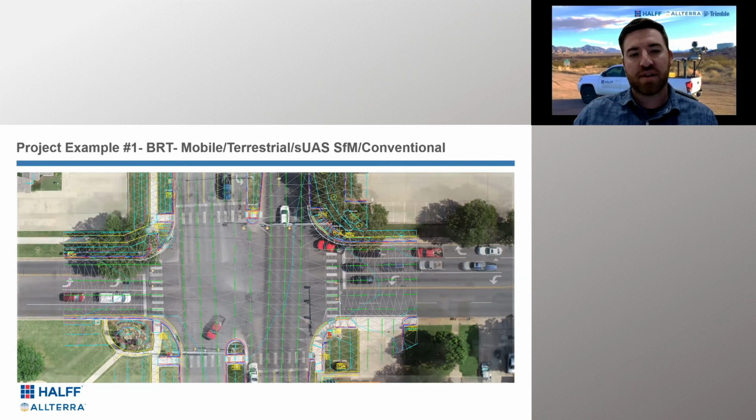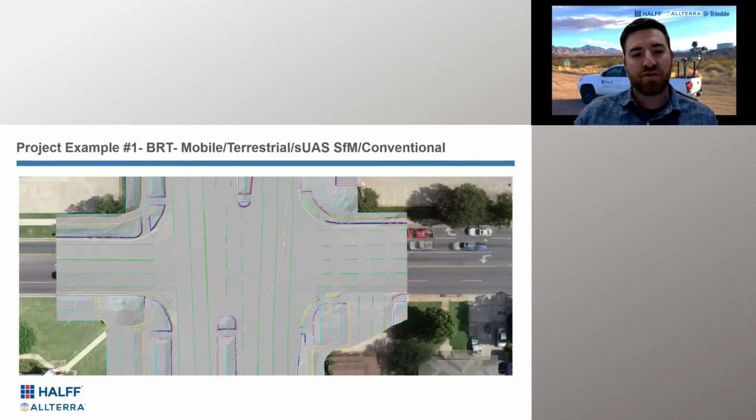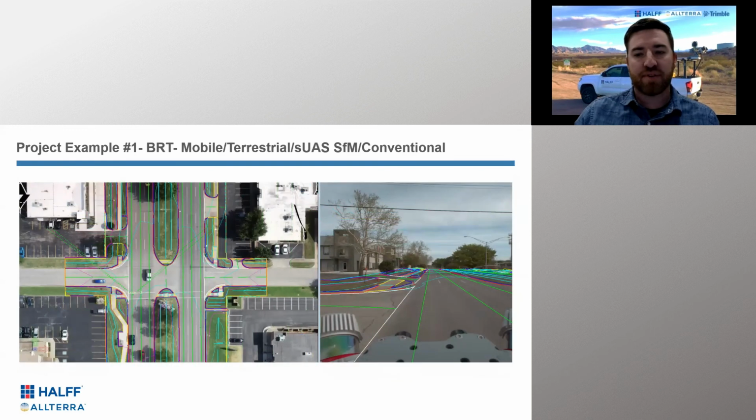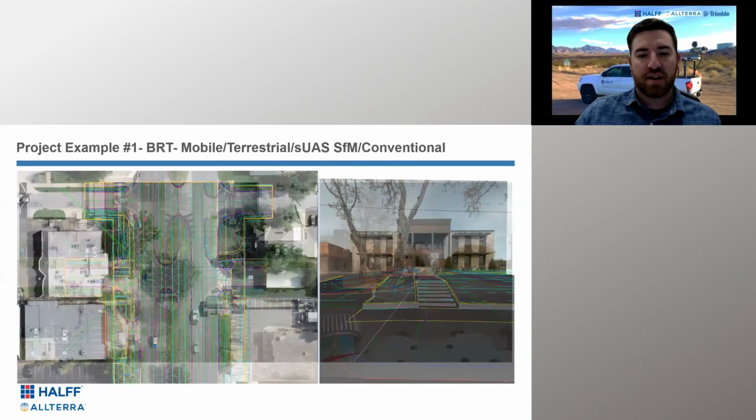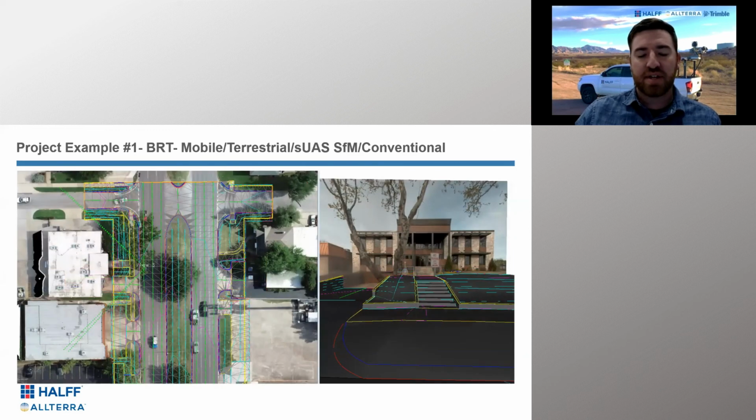And anytime you can get high res drone imagery, most surveyors would love to have it. So we use that on the corridor. Here's an example of the DTM derived from it. Another similar view to one I showed you earlier, where you're seeing all the topography derived, and then the DTM triangle file created from that.